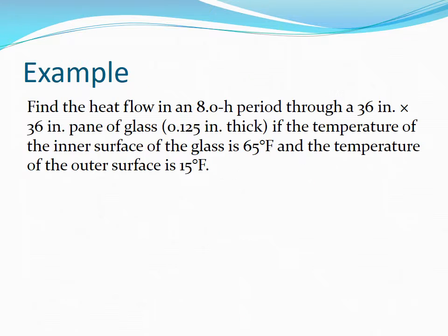Find the heat flow in an 8-hour period through a 36-inch by 36-inch pane of glass, which is 0.125 inches thick. The temperature of the inner surface of the glass is 65 degrees Fahrenheit, and the temperature of the outer surface is 15 degrees Fahrenheit.